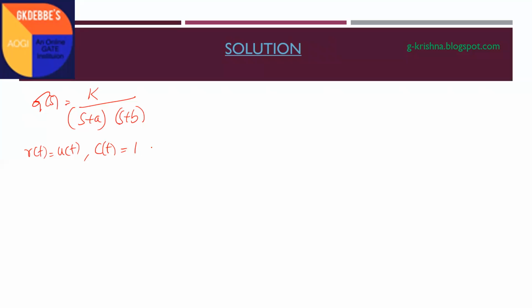That means the steady state error for the unit step input is indirectly 0, that is, output equals the applied unit step input. Whenever they apply a unit ramp input, that is t, the steady state error they want is 0.0625. To meet this data, you have to select the values of K, A and B.